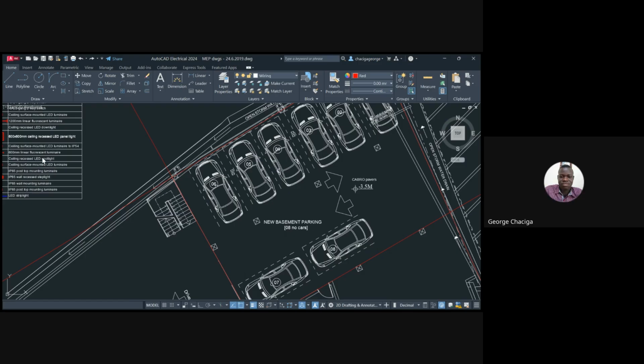So going with my 4 lighting units, you come back and select this regular distance here. We've chosen our 4 lights, but those 4 lights also have to be centered, offset from the side of the wall. So what we do, since we've selected 4, you divide by 8. Why am I dividing by 8? I'm going to see the offset from the wall.